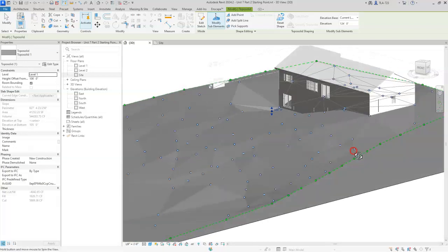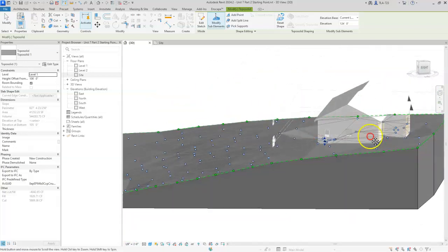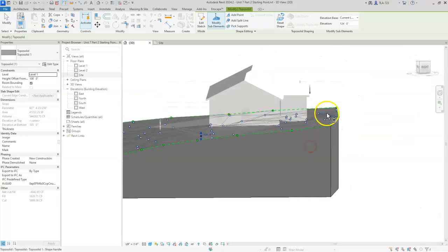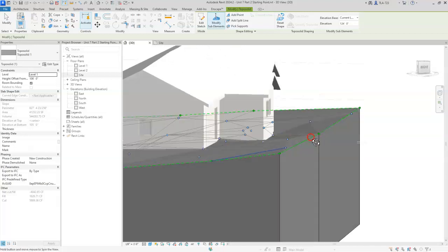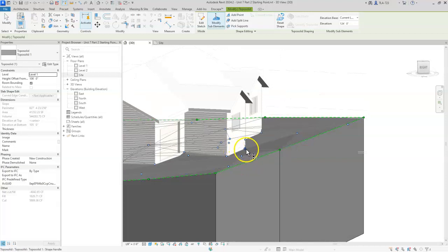Similarly, we might want to take another look at the front yard. You can see that the slope is coming down pretty quickly toward the foundation. This is obviously going to create a problem for us. When it rains, we don't want that water coming down and pouring into our foundation. We always want some positive drainage away from our house, at least a few feet.